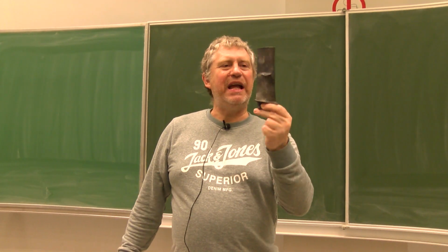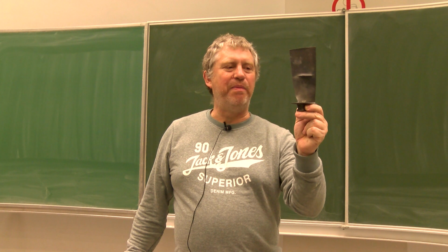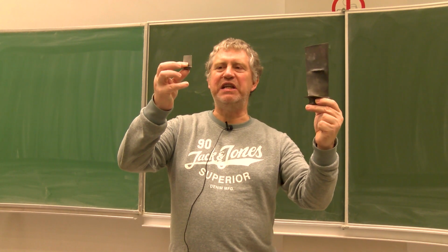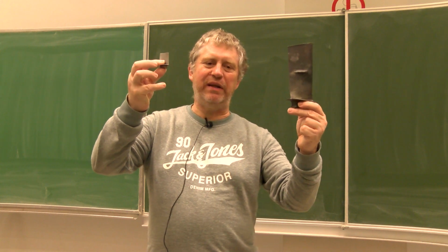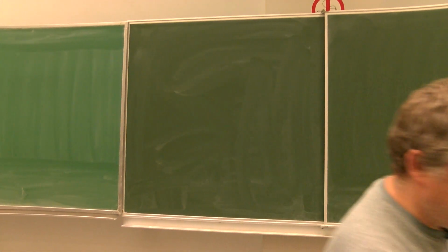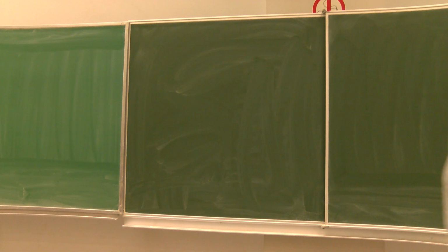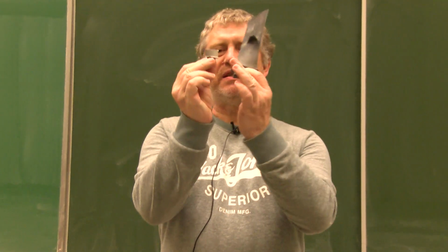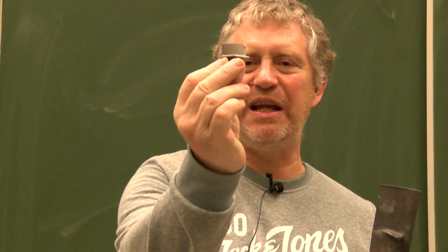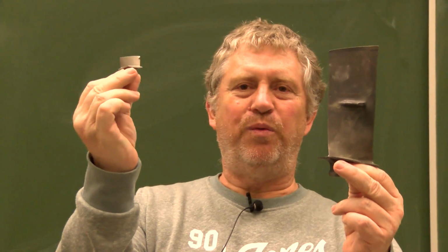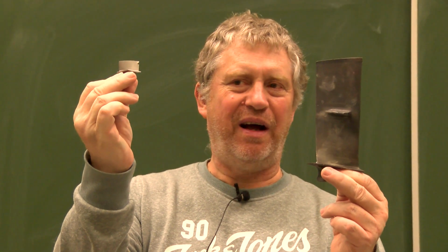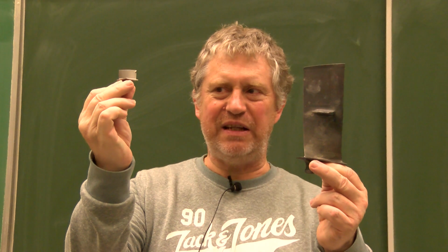Here we have H over C, which is most probably in the region of 3 or something like that. Here H over C is more in the region of 1. And you can even have something much smaller like this. So you see this blade with also the leading edge that has been degraded, which is with a H over C only something like 0.5, much, much smaller. So you see the difference.